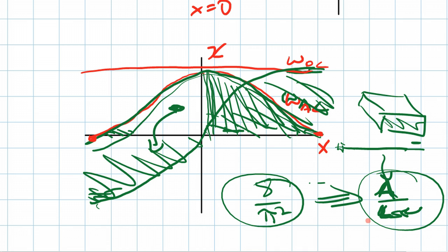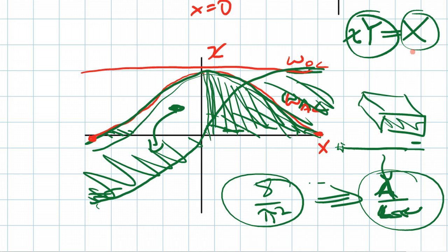It's kind of opposite to the normal convention, where in mechanical engineering we're usually used to using Young's modulus, which relates the strain to the stress. But in piezoelectricity, we're often applying some type of stress, or an electric field which causes the stress, and that causes the strain. So it's more important to consider this parameter S, the elastic compliance.